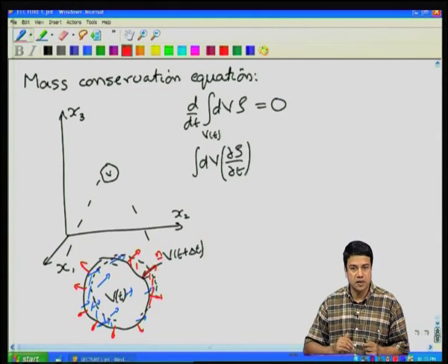Therefore, the volume that comes in is going to be equal to dS, the patch surface area, times u dot n. That increases the volume if u dot n is positive. So, if the velocity vector is in the same direction as the outward unit normal, then there is an increase within this volume. If it is negative, the patch on the surface has left behind the volume, and therefore the change in volume is negative.